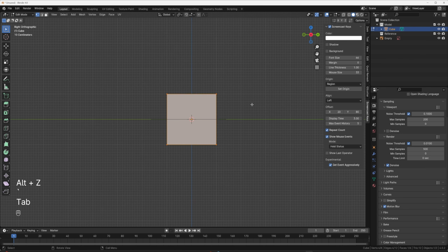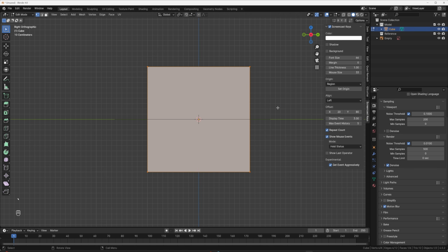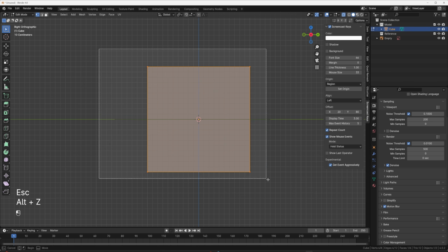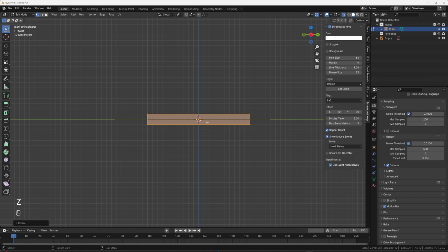I'm going to go into the right hand view, and I'm using the pie menu for that. So if you hold tilde, you can get to each of these. It's a really quick way to navigate. So I just held tilde, go to right hand view. I'm just going to SZ, and I'm going to hold control, and that's going to let me snap. And we got to make sure I'm in X-ray mode. SZ scale. I'm just going to bring it down to something that looks right.